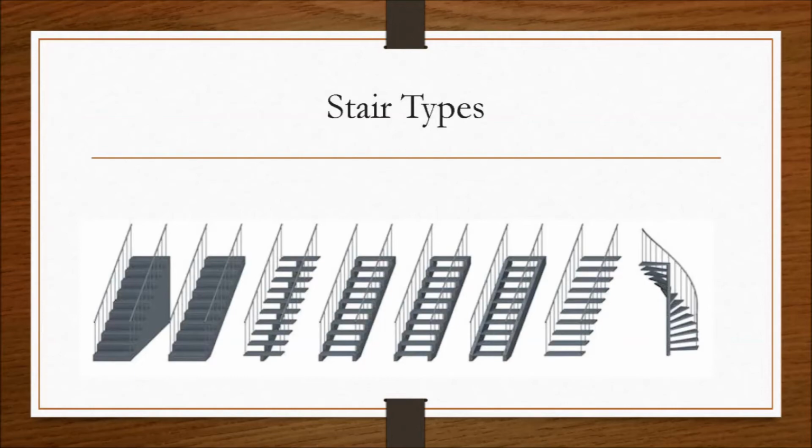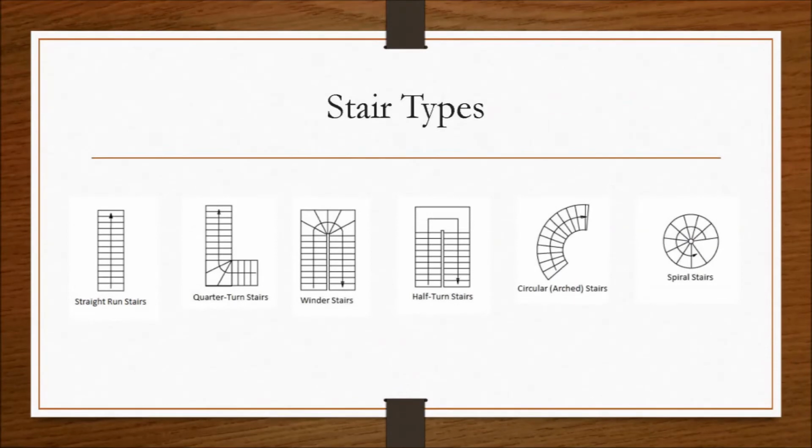The following are some criteria for stairways. A guardrail is required when the side of a stair is exposed and not enclosed by a wall. When the unusable space under stairs is enclosed, it is required by code to be 1-hour fire-resistant rated construction, with the exception of certain residential occupancy.